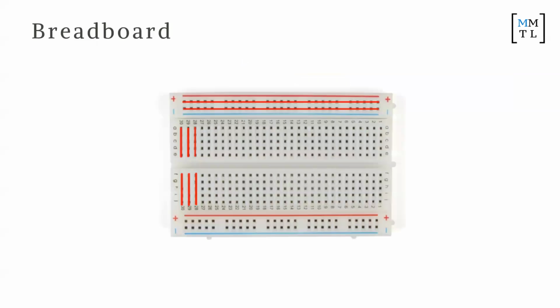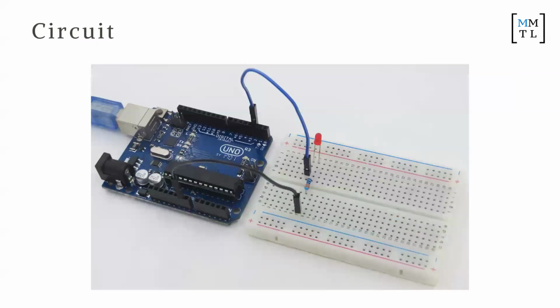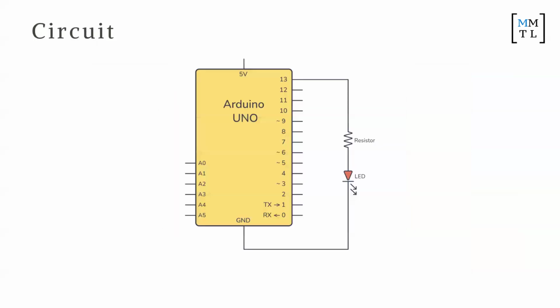And so what does that actually look like before you start? Recall that our breadboard looks like this. Please think about the breadboard before you do that. You use the male and female connectors to create the circuit on your breadboard. It doesn't have to look exactly like this, but see if you can recreate the circuit using your breadboard. We'll go around, and don't connect your Arduinos first. Let us see the circuit first and then you can connect your Arduinos later.